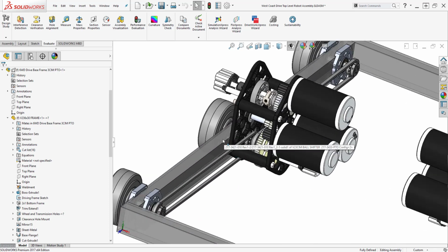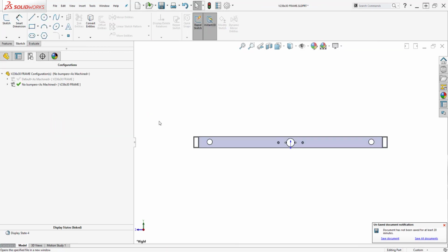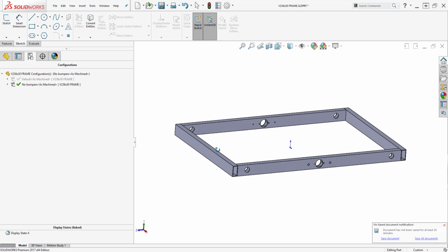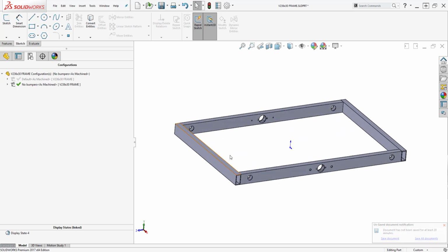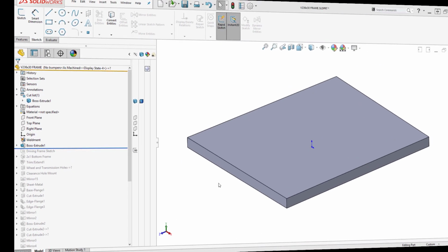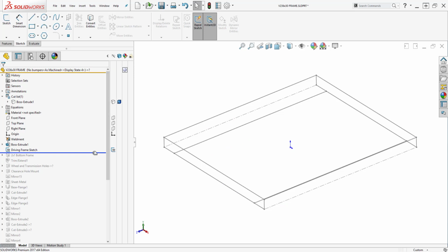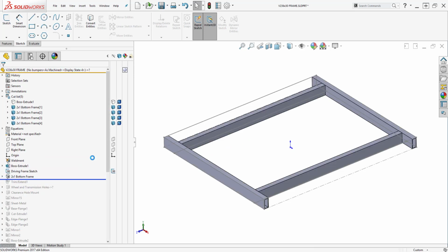To begin, I want to create a frame that automatically resizes given some adjustment, so we will begin the entire process this way. The drive rails and frame consist of 2x1 aluminum tubing with a 0.104 inch wall thickness. In SolidWorks, a 3D sketch can be used to create a layout for the frame perimeter. Using weldments, the 2x1 tubing can be placed on each line of the sketch, which creates the digital drive rails.